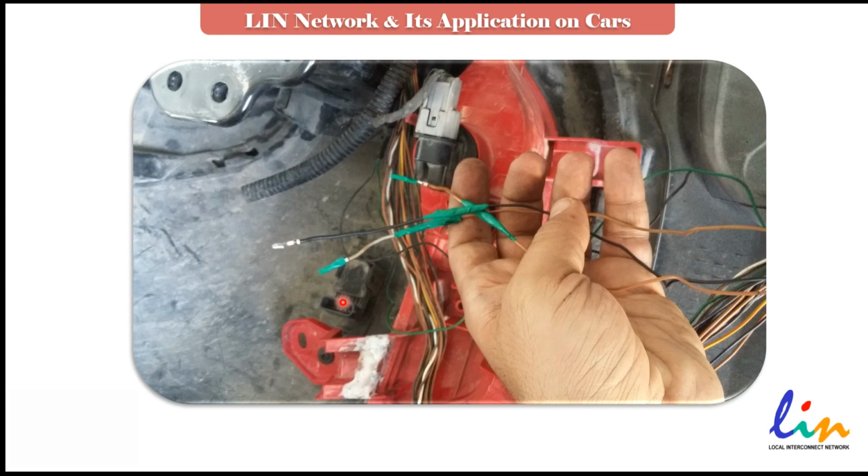So after crimping these pins on the wires and inserting them into the sensor, everything started to work as normal, and we didn't have the fault code anymore, because obviously, technically, they cut the wire, and cutting the wiring caused some short circuit as well. So we had this problem on the LIN network.